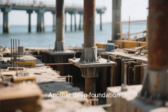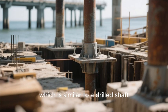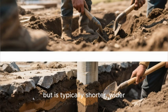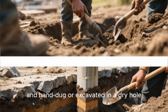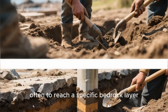Another deep foundation type is the pier foundation, which is similar to a drilled shaft but is typically shorter, wider, and hand-dug or excavated in a dry hole, often to reach a specific bedrock layer.